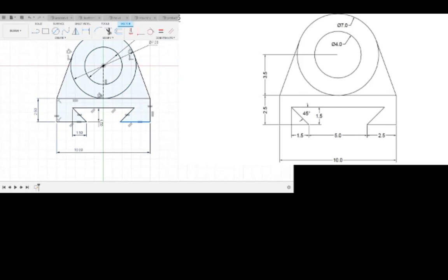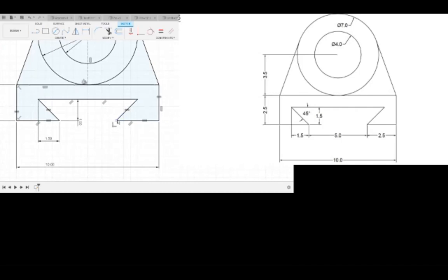So that's a problem. What is missing here? Something is missing here. What would that be? Right. For some reason, Fusion did not want to show that this point was unconstrained. So it's not actually done. Which is very strange because often sketch points should be displayed as unconstrained so that you don't make this mistake, because all the lines are black. But I guess that's a reason why we don't really use Fusion. Because you need to set this relative to the center line, but since this is symmetric about the center line, you don't need to use the symmetry mate or symmetry constraint.